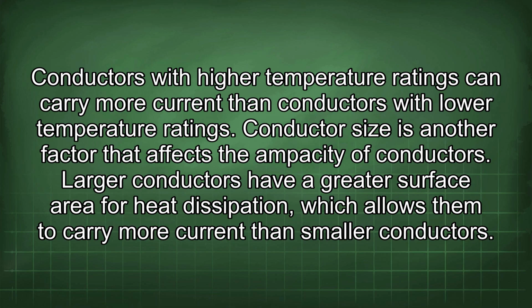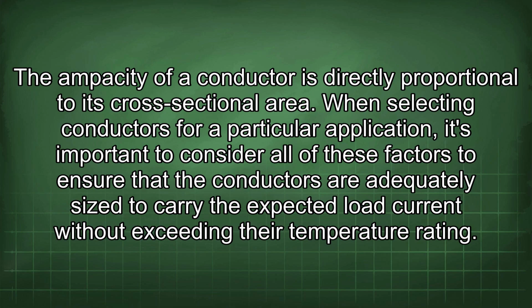Conductor size is another factor that affects the ampacity of conductors. Larger conductors have a greater surface area for heat dissipation, which allows them to carry more current than smaller conductors. The ampacity of a conductor is directly proportional to its cross-sectional area.